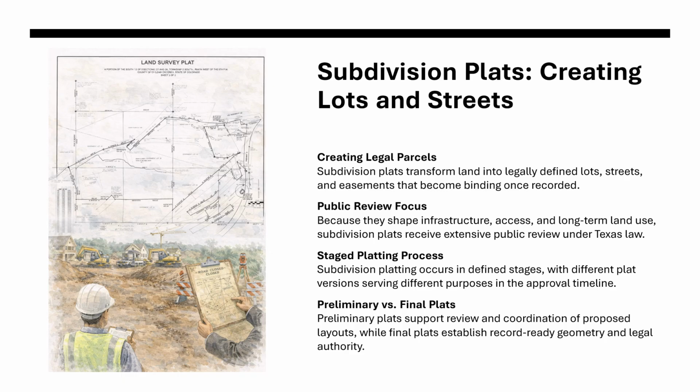For students, this is also where theory begins to intersect with professional practice. Concepts like lot layout, right-of-way width, and easement placement are introduced abstractly in coursework, but subdivision platting is where those ideas are translated into legally enforceable form. The difference between a conceptual design and a final plat is not just precision, it's permanence.